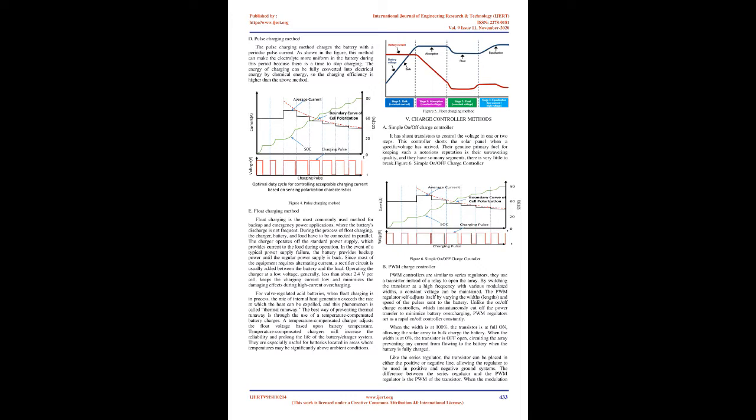D. Lead-acid battery. These batteries are most commonly used in automobiles and used to store solar energy because they can provide high current, and their cost is relatively low. They hold only about 25 watt-hours per kg. Each cell consists of lead electrodes in a sulfuric acid solution. Electrodes are made out of lead and coated with lead oxide. Connecting 6 of these cells in series gives a 12V battery.